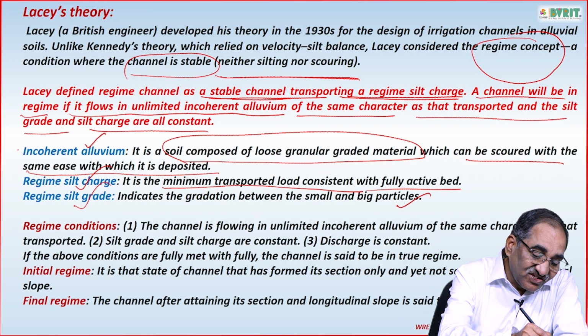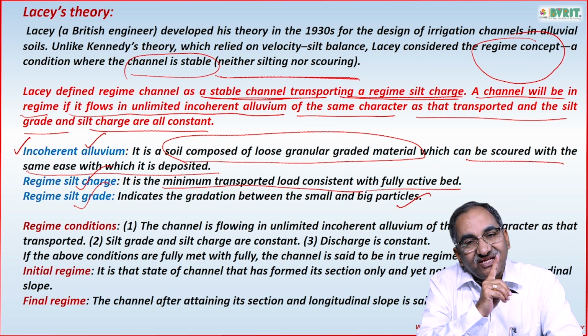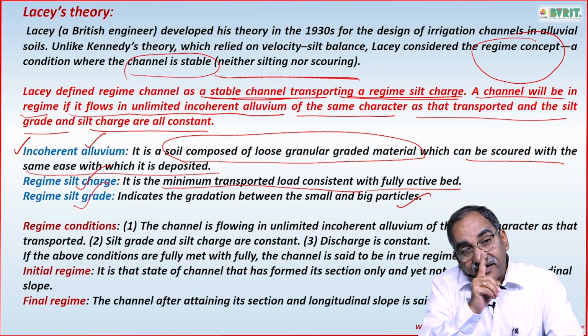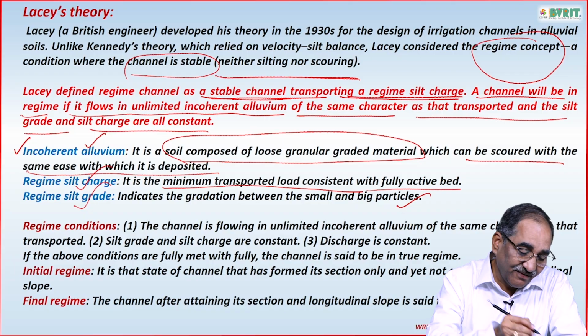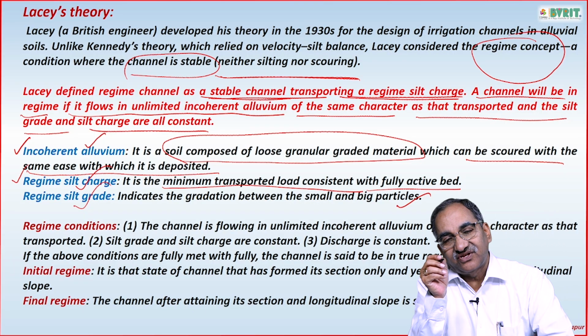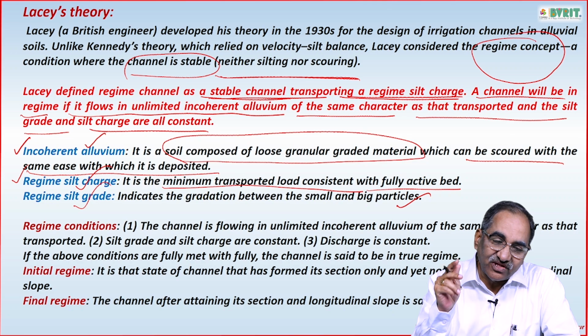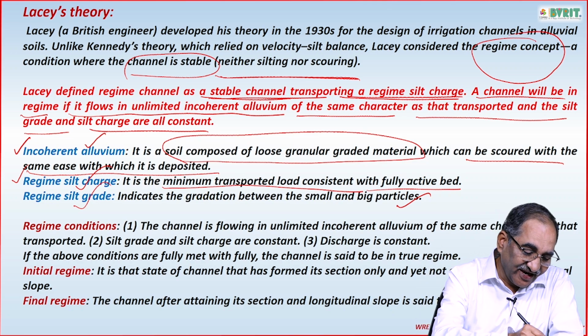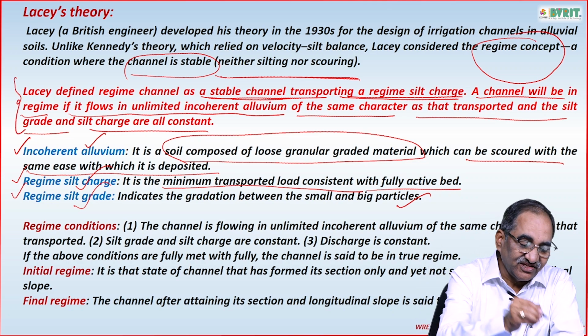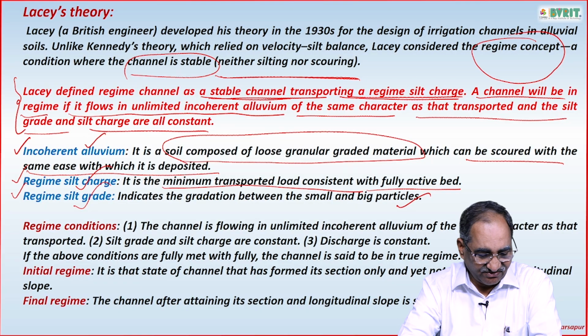So three things are there. The channel is passing through an unlimited incoherent alluvium and it carries a regime silt charge and silt grade. Both are constant. That is the next thing. That is what Lacey has mentioned as a regime channel.